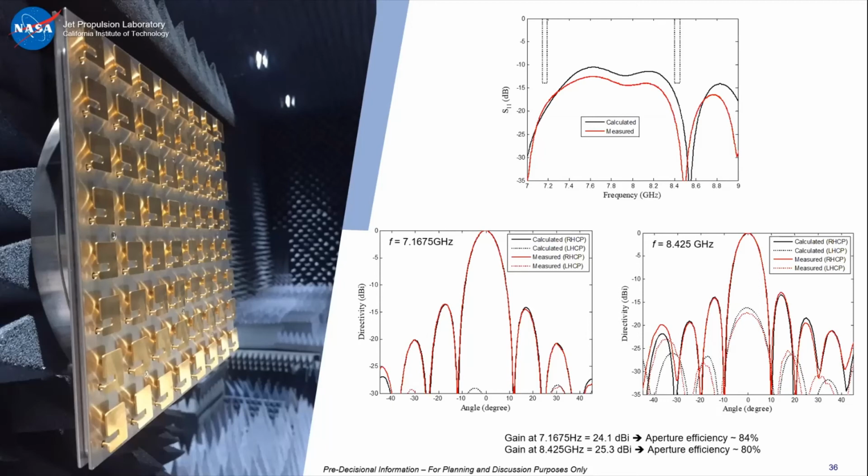Now, you were trying to qualify this at cryo temperatures also. Has it been qualified, and then you do the measurement? The way we qualify over thermal is that there are different types of tests. There is a thermal cycling test where we verify that the antenna is surviving. So we have a survival range. It will be passive during that time? Yeah, for survival it's passive, but for operational we're actually checking the S parameter of the antenna.